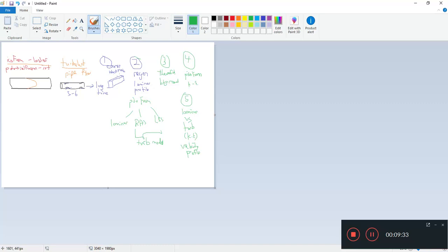We want to redo our snappyHexMesh thing. Hopefully that turns out well. We want to regenerate a laminar profile using pisoFoam. And then we want to look into the theoretical background behind turbulence and study this thing called the K epsilon model and what other models there are, and why we are doing what we are doing for turbulence. Then we want to use pisoFoam with the K epsilon model. And then finally, we want to do some post-processing. So this is very important, post-processing.